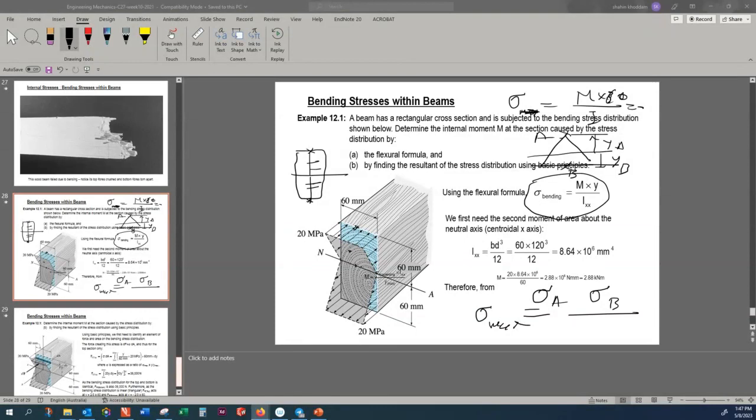So with a beam subjected to bending, for one given cross section, the largest normal stress is at the point which has the largest distance from the neutral plane. Everyone agrees with that conclusion? So we are generalizing that example. The example was for the triangle. For the case of the rectangle, the maximum stress is either at the top or at the bottom. They're equal in absolute value, but one of them is positive, one of them is negative.